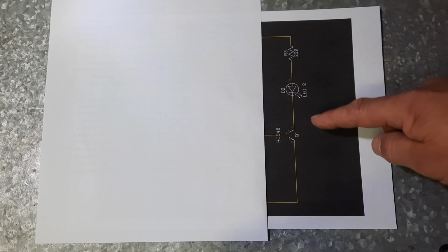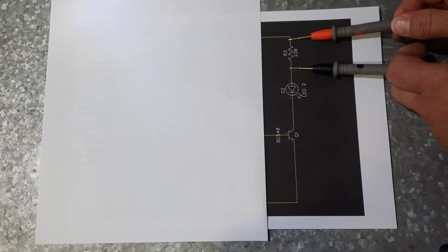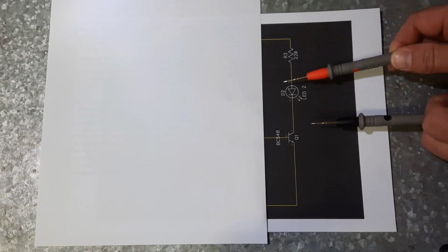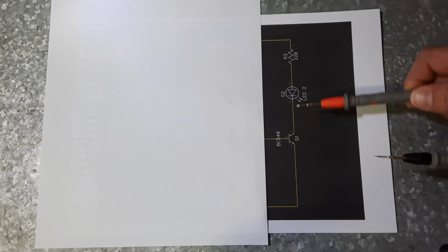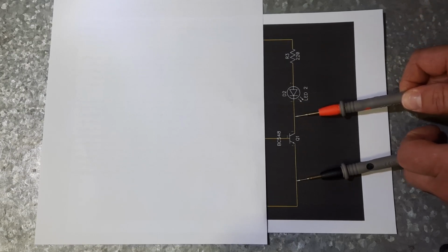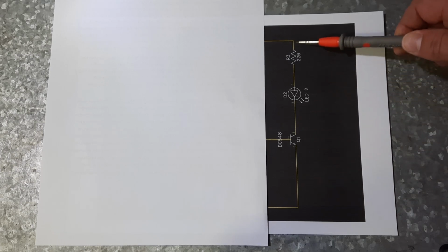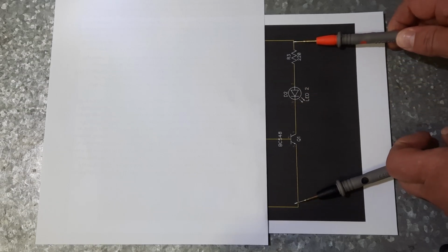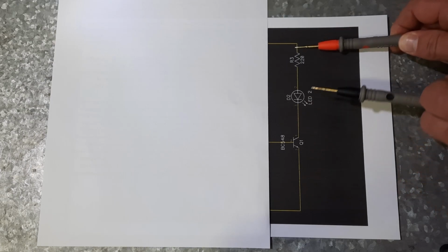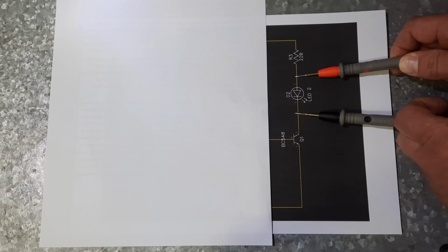And there are 2 volt drops across this, because if we got our voltmeter and we measured from here to here, there would be 1 volt drop. If we then measured from here to here, there'd be another volt drop. But with this switch closed, we could measure from here to here and it would be 0. There's still current flowing through it, but the 2 volt drops are occurring across these 2 components. So from here to here, we would have 9 volts. From here to here, we'd have about 6.6. From here to here, we'd have about 2.4.